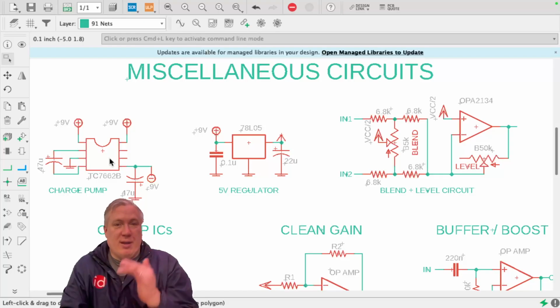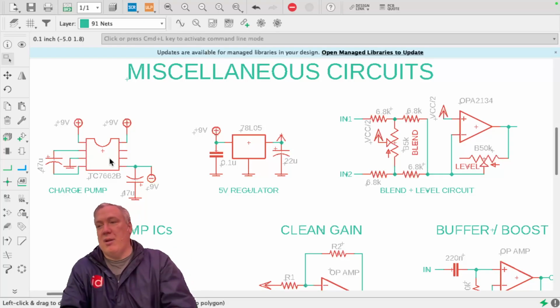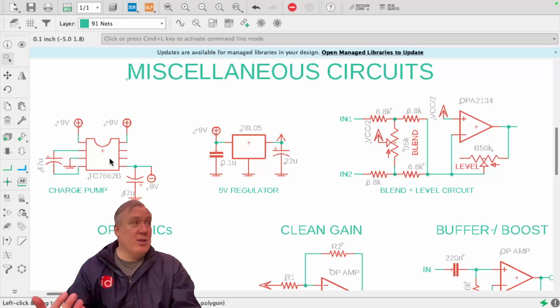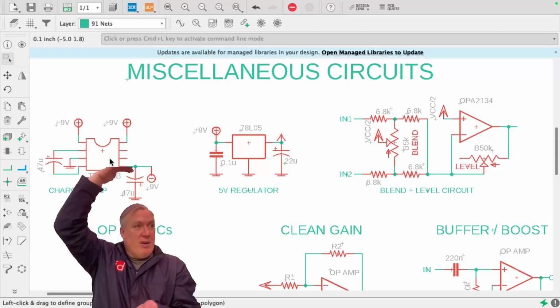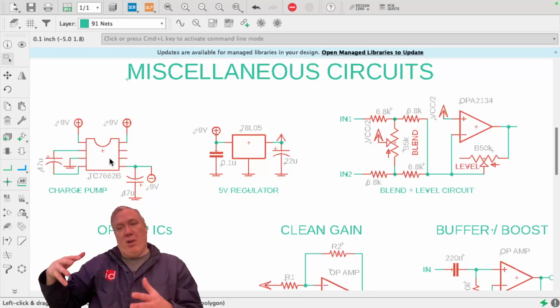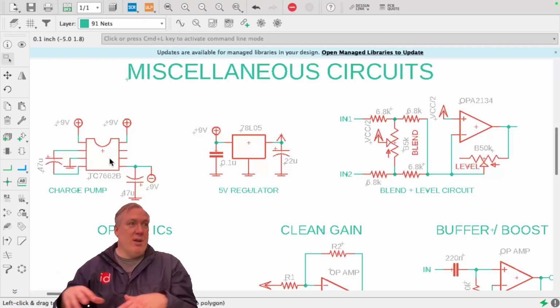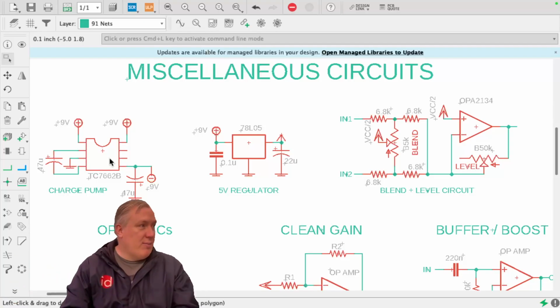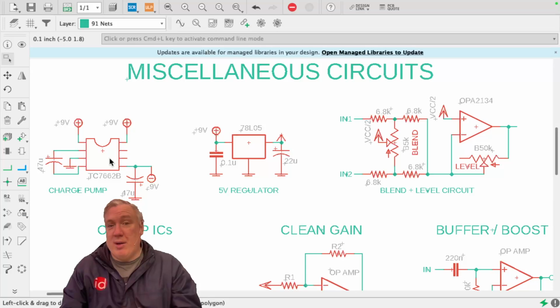I adapt this so that my circuits can, even though you can only plug in 9 volts, which is the industry standard, run essentially on 18, because plus 9 and negative 9 are 18. And that makes them run more like professional studio gear than like battery-powered effect pedals, which can make them sound better in certain situations, or just at least different.